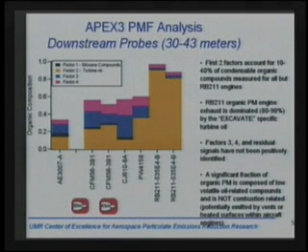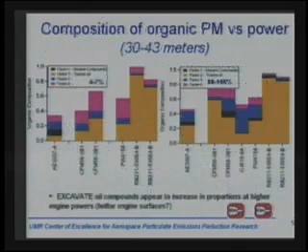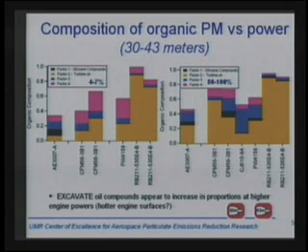What started in a preceding study called Excavate, but has gone out through the Apex series, is to try and do the fractionation from the AMS. I don't really have time to go into this in gory detail, but I will point out that we are seeing contributions both from something that we can associate with lubrication oil, as well as that due to incomplete combustion hydrocarbons from the fuel. And it varies from airplane to airplane, which engine technology is associated with it. Engine oil isn't typically a thing people worry about from emissions. It's not clear whether one needs to or not. But as a result, the different manufacturers deal with lubrication oil in different ways, and that results in different contributions to the organic fraction that we're measuring with the AMS in the particle phase.